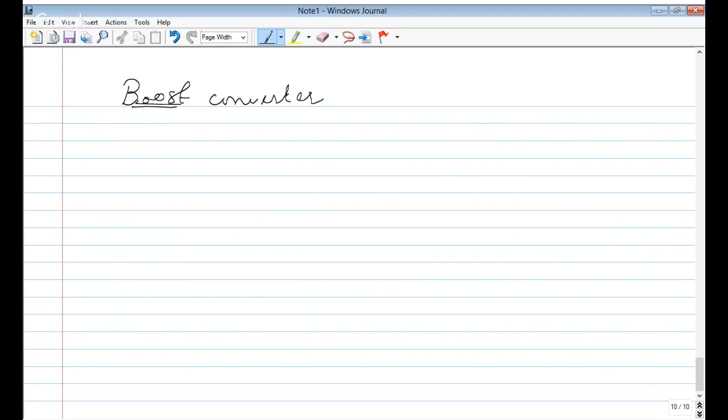So what I'll do is we will find V naught. V naught is Vs by 1 minus D. So how much will it come out to be? 400 by 0.45. Now once we have V naught, it is basically EMF plus IA into RA.